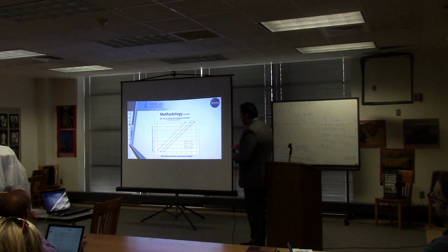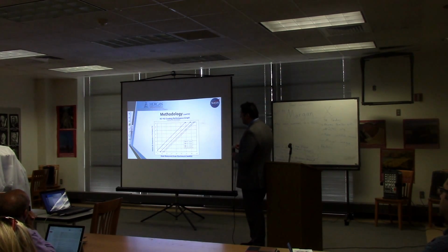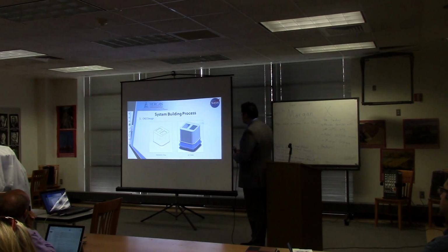This is another graph that shows why I picked that specific cooling system. I want to be at 22 degrees when the ambient is 0 degrees centigrade. So it brings us down here, which is between 80 and 120, mostly 100, and that's my maximum loss, and that's what I need to cover.